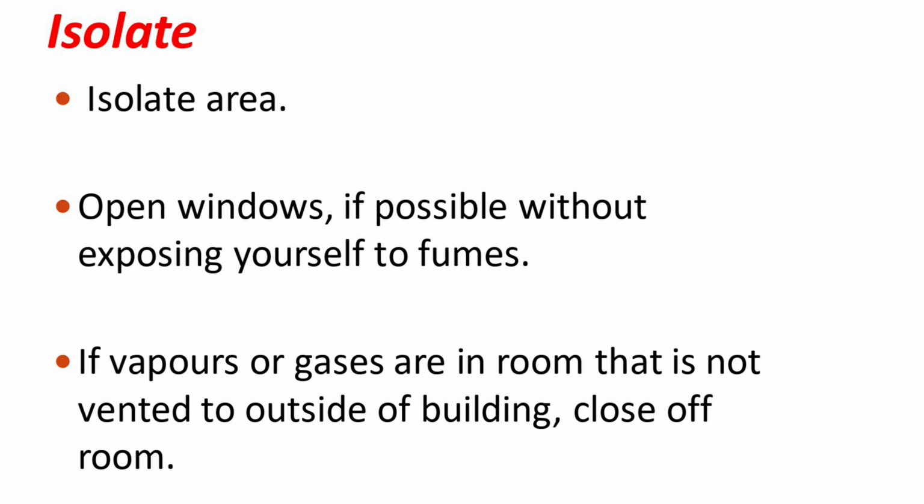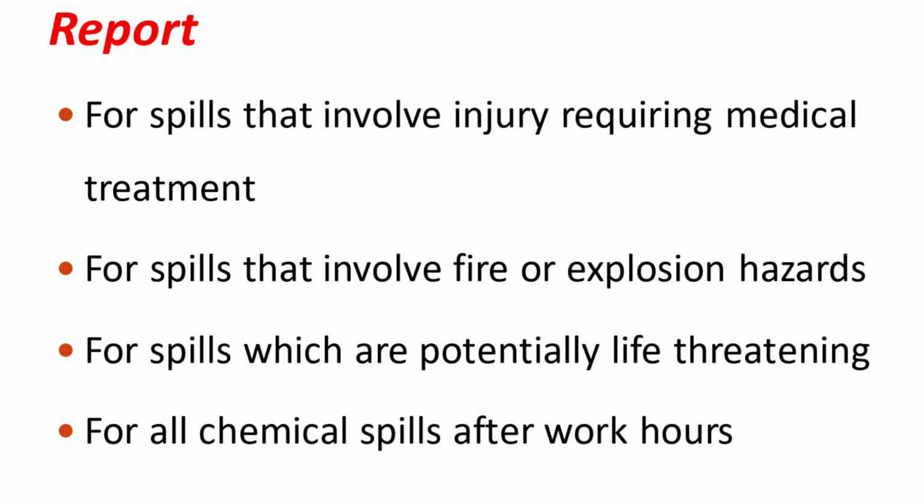Isolate area. Open windows, if possible, without exposing yourself to fumes. If vapors or gases are in a room that is not vented to outside of building, close off the room. Report for spills that involve injury requiring medical treatment, for spills that involve fire or explosion hazards, for spills which are potentially life-threatening, and for all chemical spills after work hours.